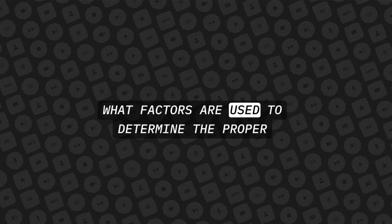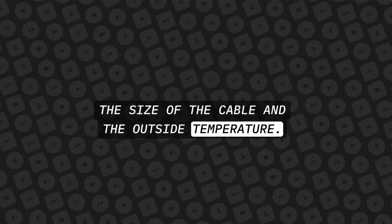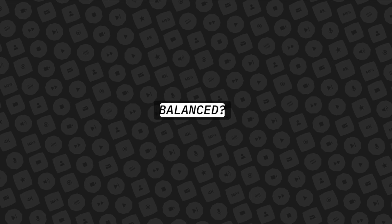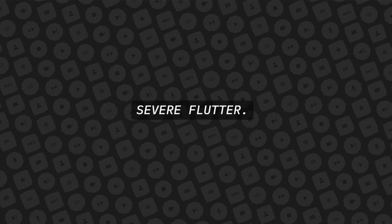What factors are used to determine the proper cable tension? The size of the cable and the outside temperature. Why do control surfaces need to be statically balanced? Because an out of balance control surface can cause severe flutter.